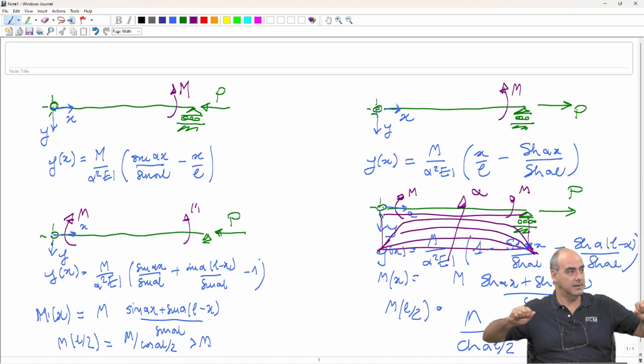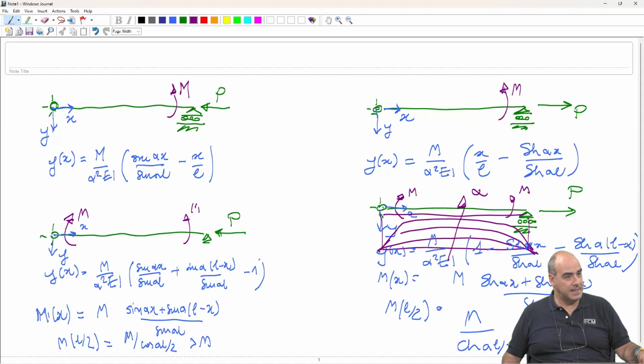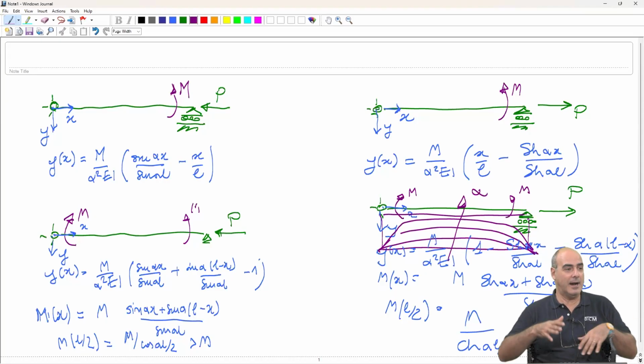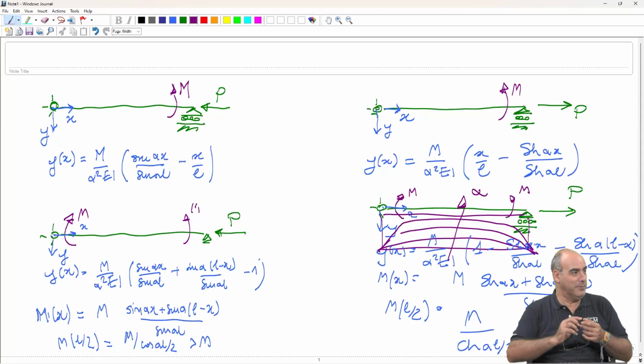Tying it. So as we said, we can see the effect of a compressive axial force as something which decreases the stiffness. The tensile axial force, on the opposite, increases the stiffness. Well, another example is, you know, these acrobatic people that run with a bicycle over a rope. If the rope is not stretched, it cannot carry. And if the rope is not stretched enough, the rope goes down, and they are not able to go up. So, you know, these are very simple examples, but they allow us to understand.